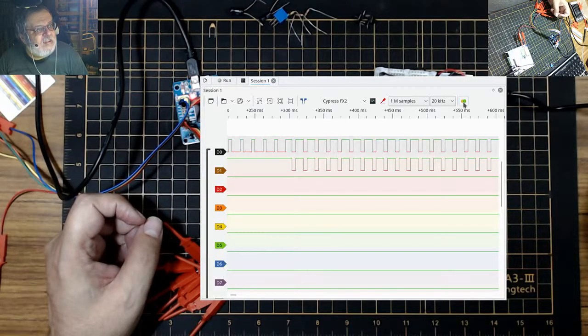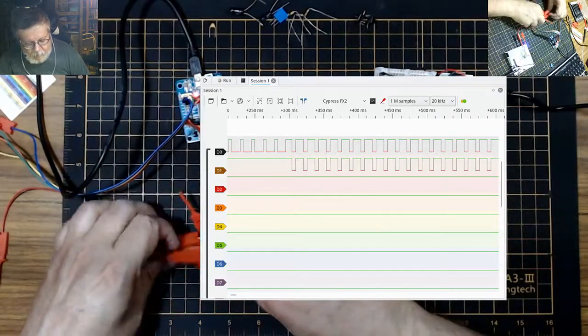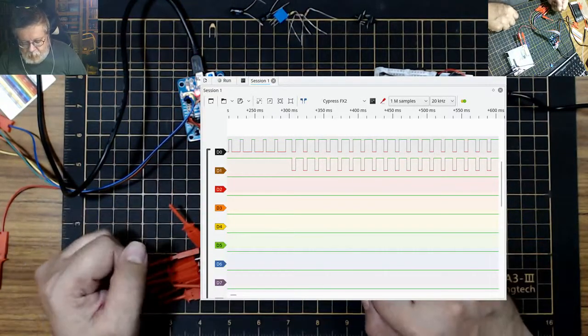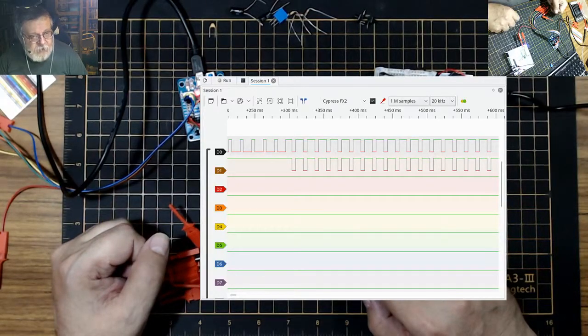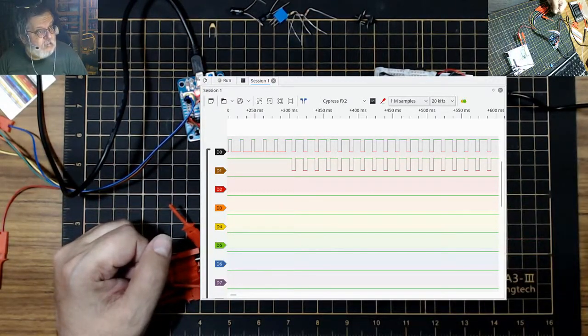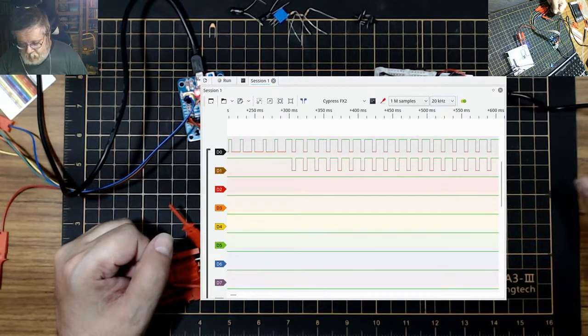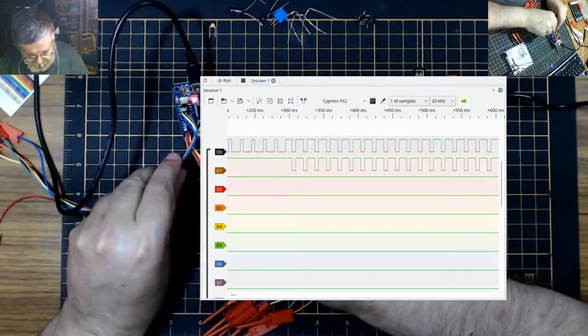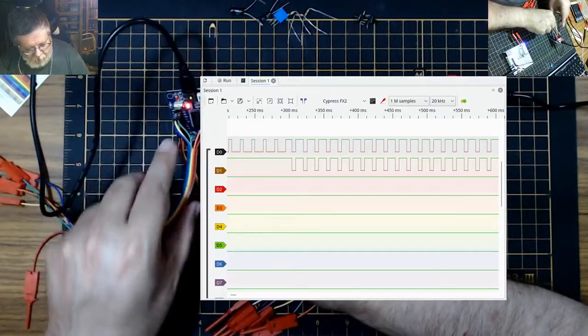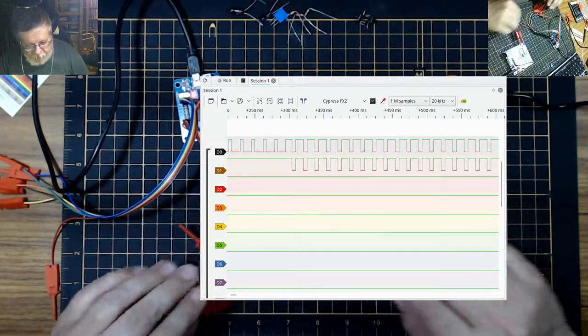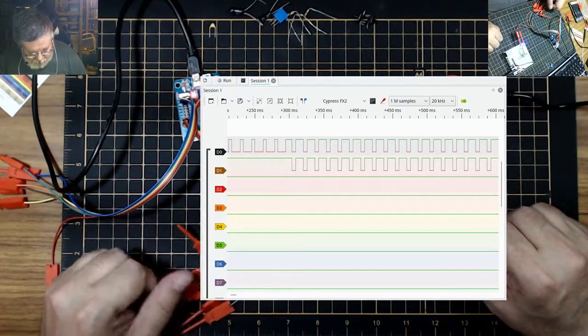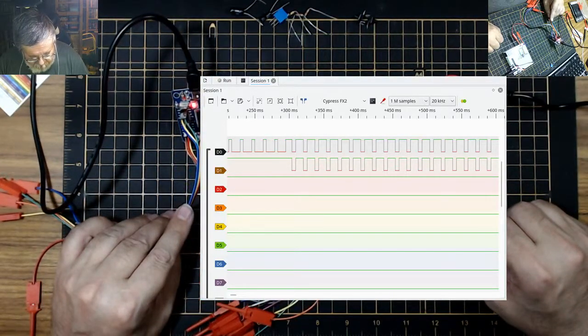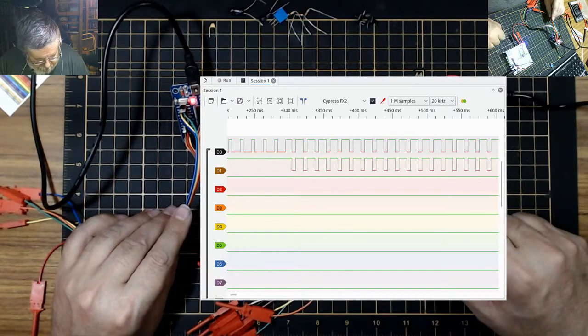Now I don't know what this green thing does. Add low-level non-stack protocol decoder. Oh, okay. I think now I understand what that one is for. I could hook this up to, let's say, serial, and I should be able to decode the serial as it comes through. But yeah, this is a really fun toy to play with because it's kind of interesting, without having to go out and buy a multi-$1,000 expensive logic analyzer.